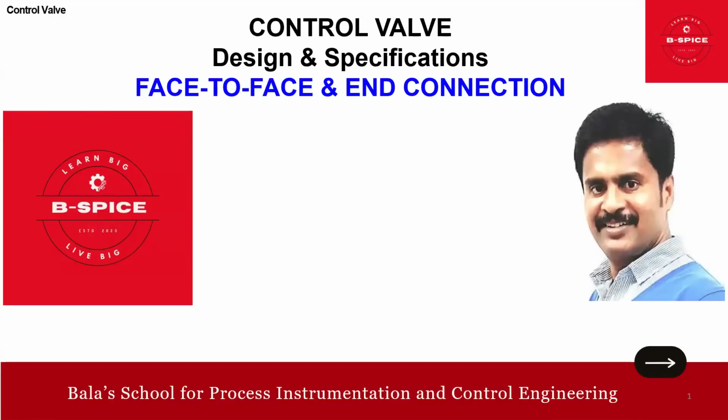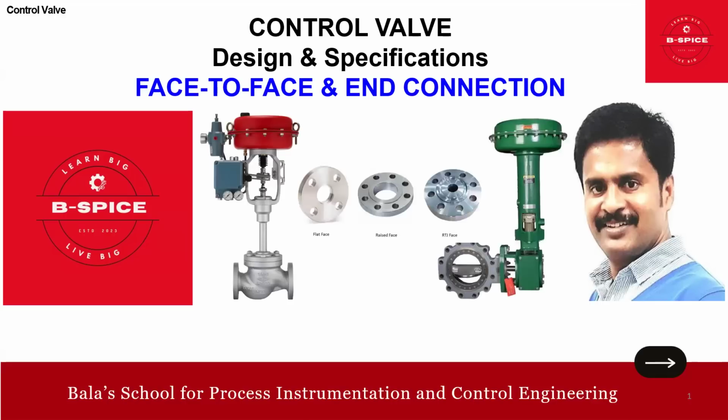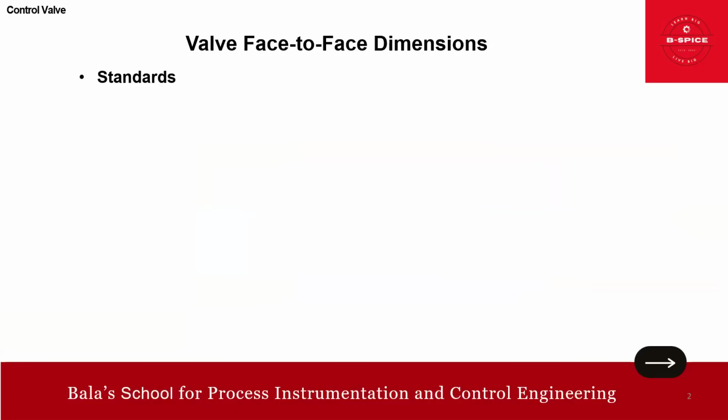In this session, we'll continue with the control valve design and specification, wherein the focus is more on face-to-face and end connection. Face-to-face in the sense, what type of face, whether it's a flat face, raised face, or ring type joint face, and what are all the criteria involved, and also the end connections, and of course a bit of standards. All these we are going to cover. Okay, friends, let's get started with the standard valve face-to-face dimension.